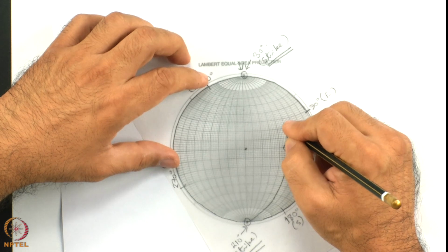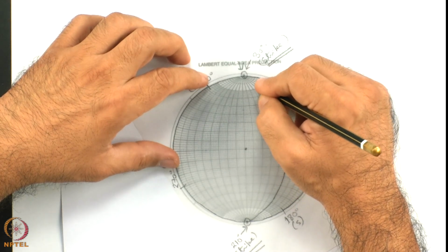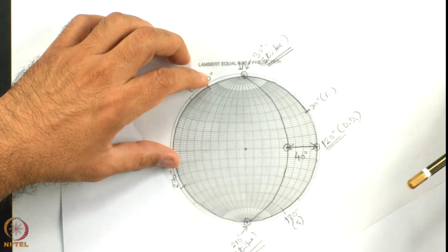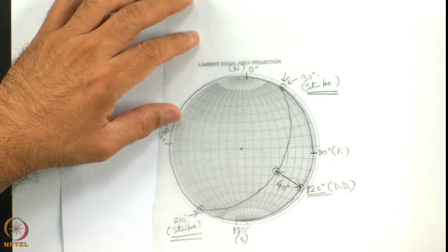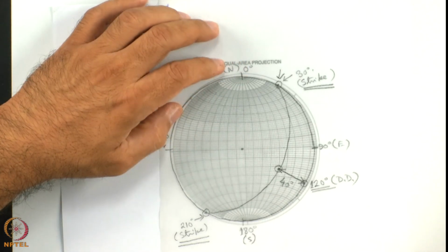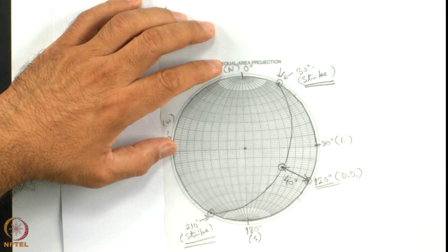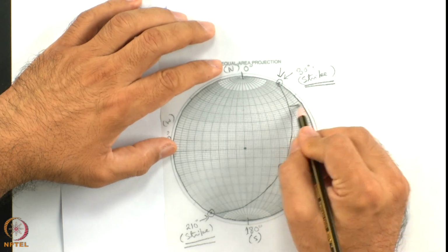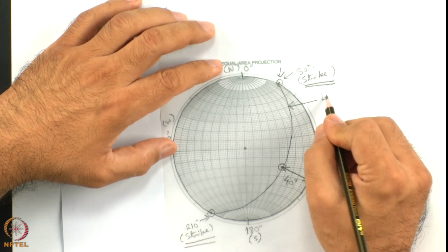So, I am following a mid path, not too fast, not too slow. Now, if I move back, match 0 degree with the 0 degree of the Stereonet, a great circle is drawn, and this great circle represents the lithological contacts which are parallel.